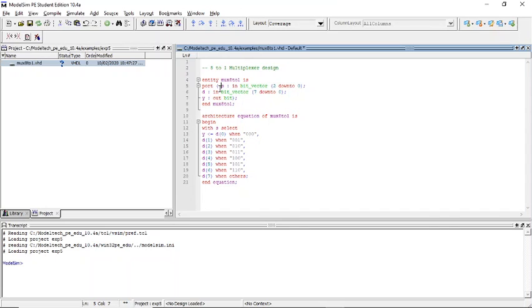By looking into the block diagram of 8:1 multiplexer, it has 3 selector inputs. We'll declare the selector input as a bit vector, which is similar to array in C. So the size of the bit vector is 3, that is index 0, index 1 and index 2.